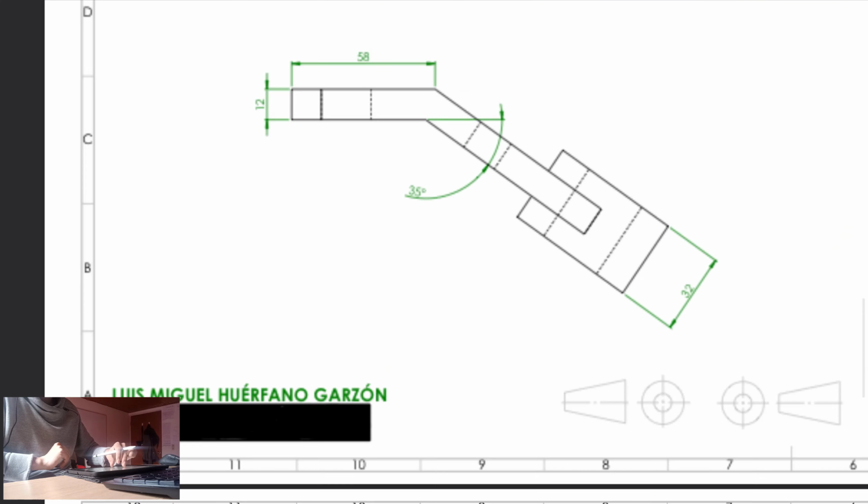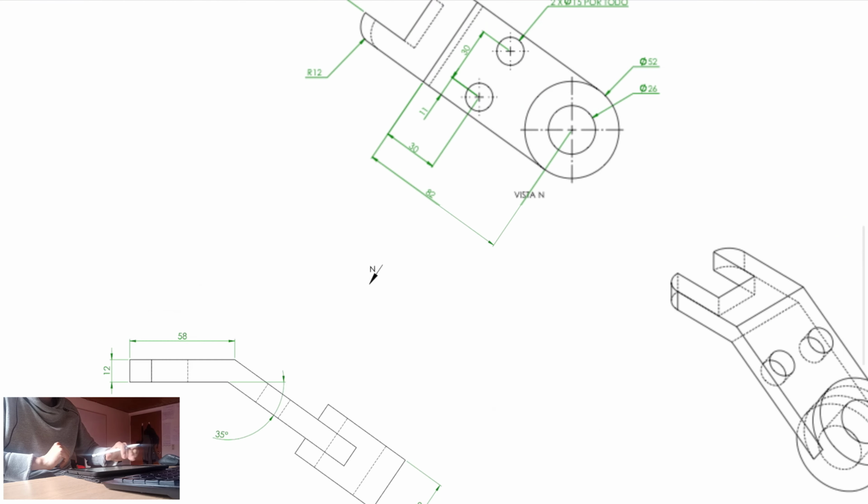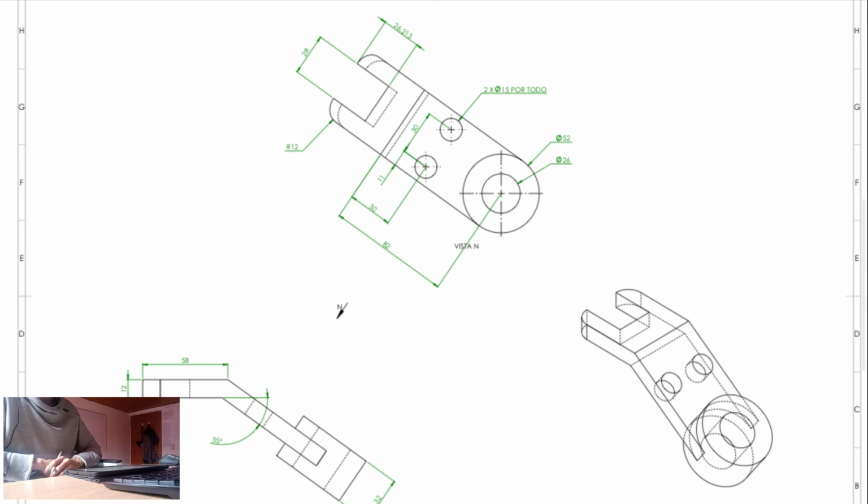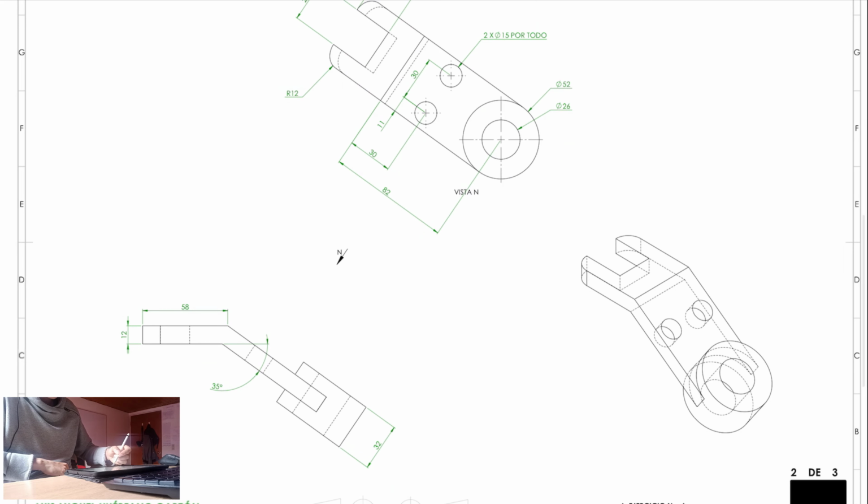I was able to identify some different mistakes done with this engineering draw. The first one, I cannot see any information within a box regarding the unit system, the name of the part, the material. This is pretty crucial information for when you want to manufacture a part.